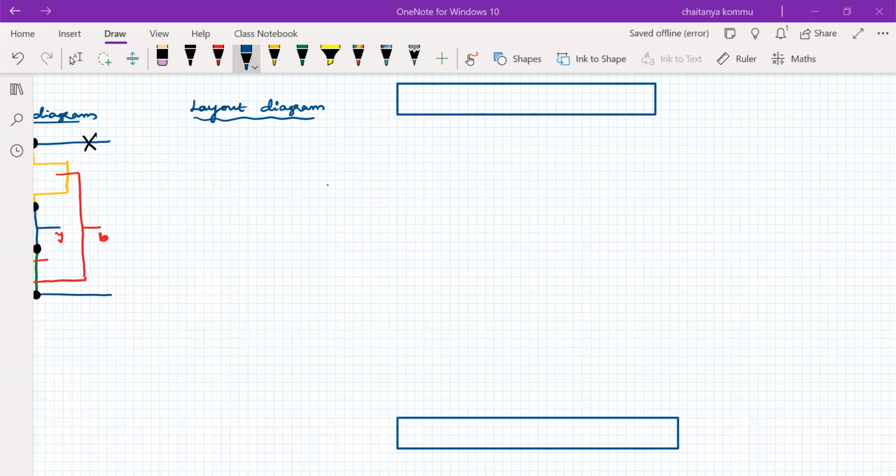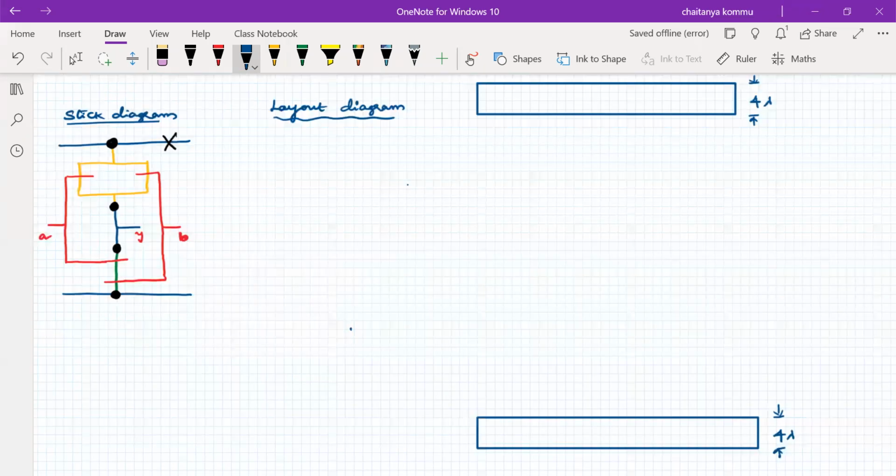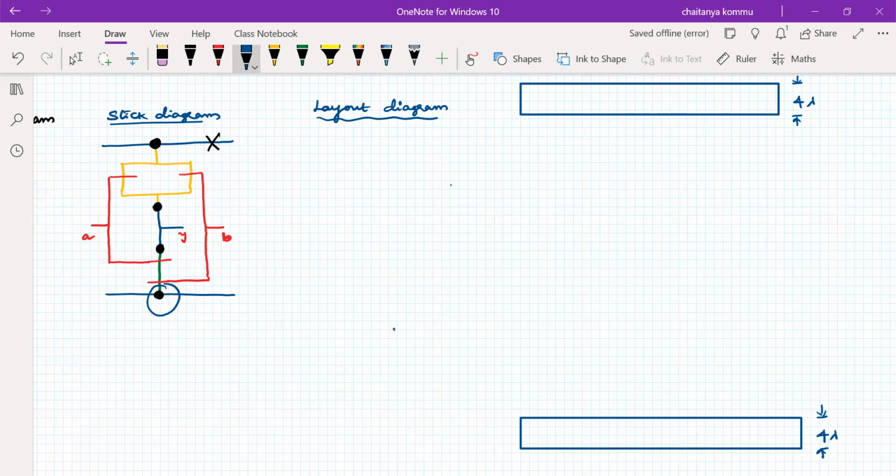So what is the minimum width of this metal line? This is for VDD. The minimum width is 3 lambda we have to maintain here. So minimum 3 lambda, but I want to consider 4 lambda. Why? Because the contact overlap region I want to use is 4 lambda by 4 lambda. Therefore, that's the reason I'm interested in using a metal width of 4 lambda. 3 lambda is sufficient, there is no doubt at all, but for the sake of the contacts, this type of contacts I'm using, the overlap region is 4 lambda by 4 lambda. That's the reason I want to extend the metal to 4 lambda, not 3 lambda. But if you're not interested in using 4 lambda, use 3 lambda only.